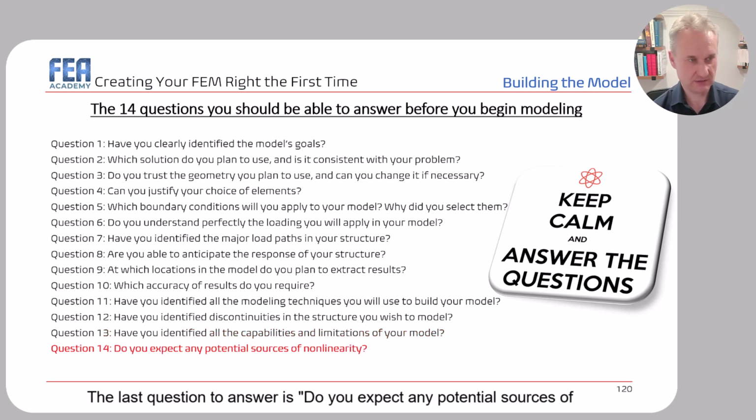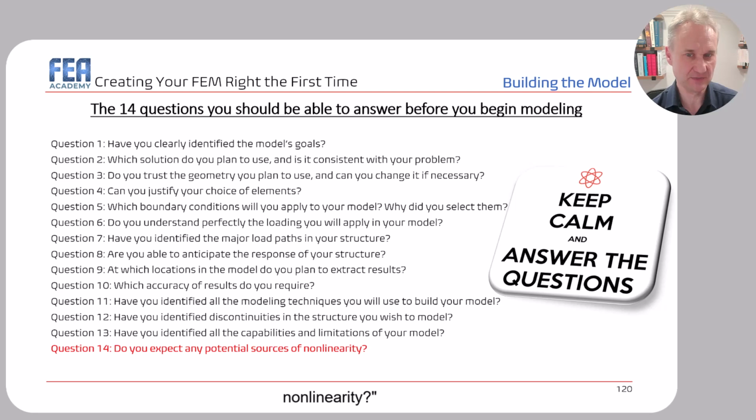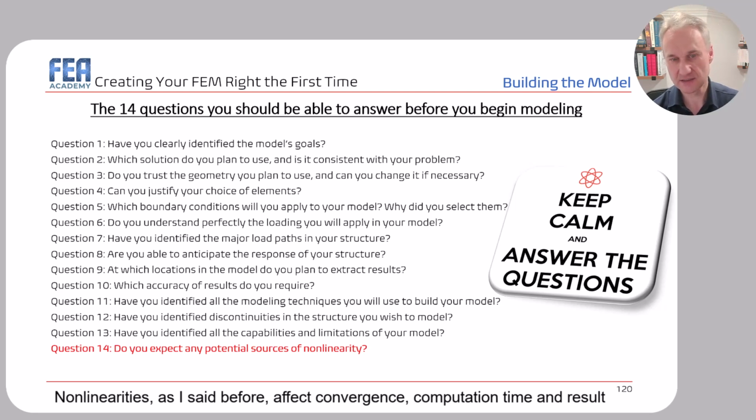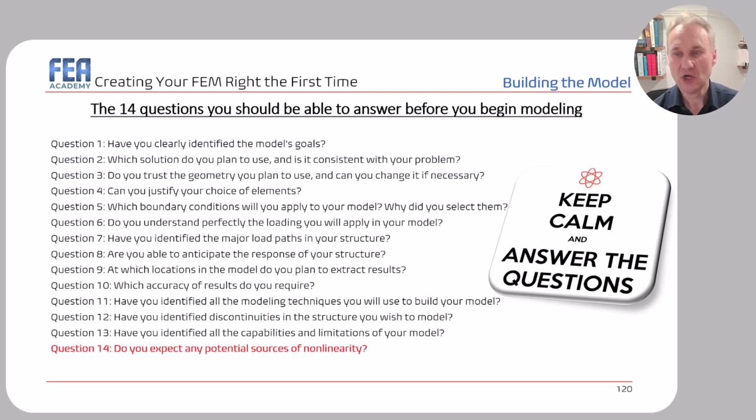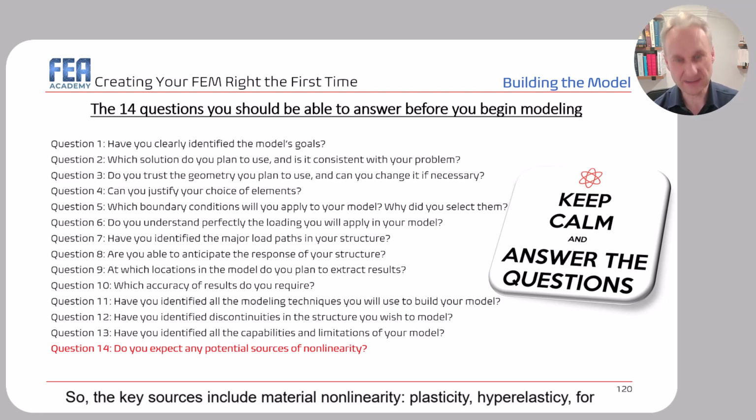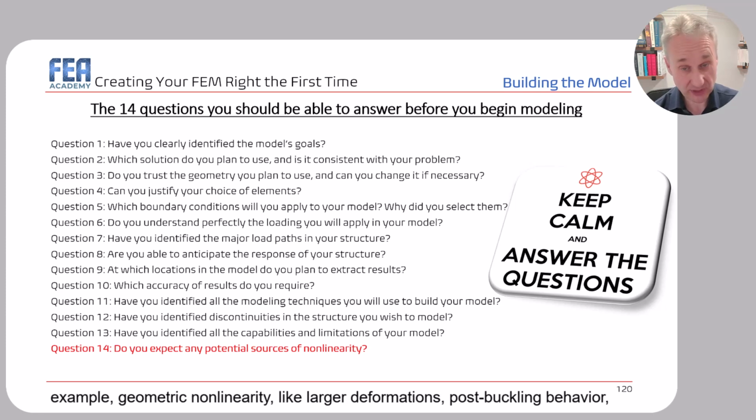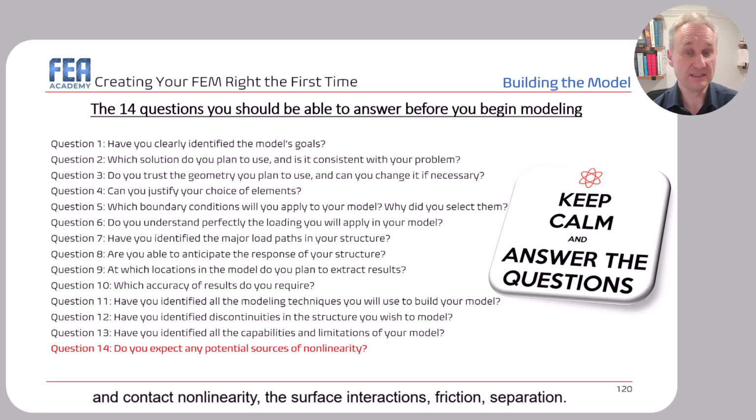The last question to answer is, do you expect any potential sources of nonlinearity? Okay, nonlinearities, as I said before, affect convergence, computation time, and result accuracy. So the key sources include material nonlinearity, plasticity, hyperelasticity, for example, geometric nonlinearity like large deformations, post-buckling behavior, and contact nonlinearity, the surface interactions, friction, separation.